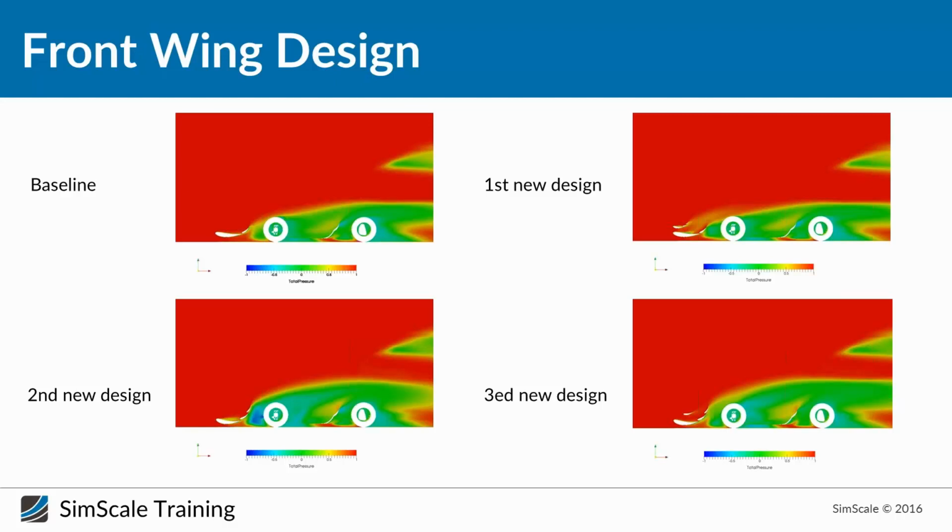I think for our simulation it's 20 meters per second, and I don't know if you agree with me or not, but at this speed the diffuser will not really have a huge effect or will not work at low speeds. It's better when you move at high speeds, then the diffuser can have an effect, and this is according to the results that we get. So for example, the diffuser generates sometimes like 20 or 30 newtons, while the front wing and the rear wing generate around 200 newtons.